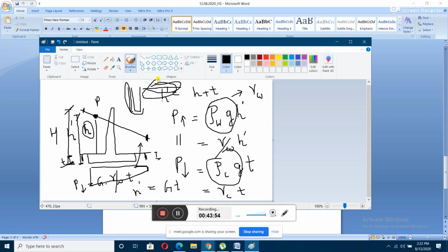He took the same value for creep, he took this as d1 and also for this one as d1, but here the outer surface is much more effective. It will provide more resistance to the flow than your inner surface. So he did not distinguish between the inner surface and the outer surface. The outer surface provides more friction than your inner surface. That is another limitation.